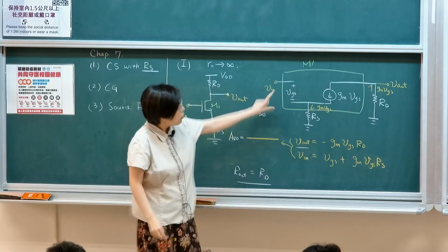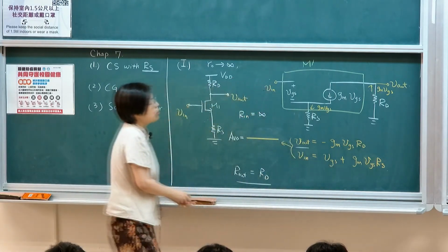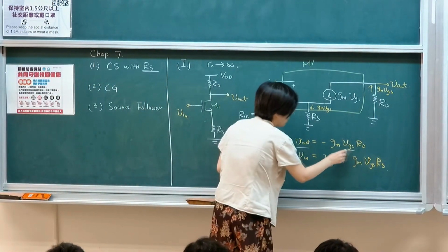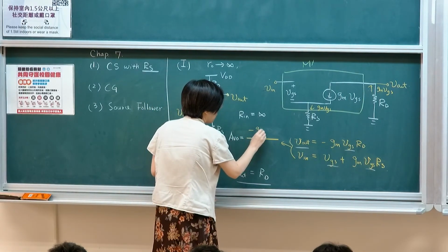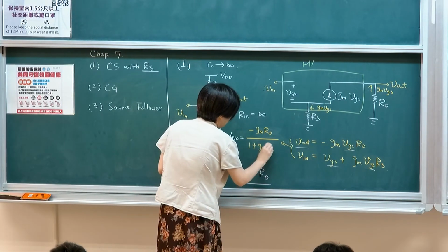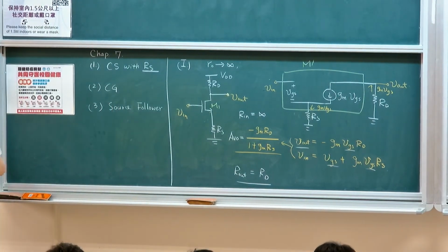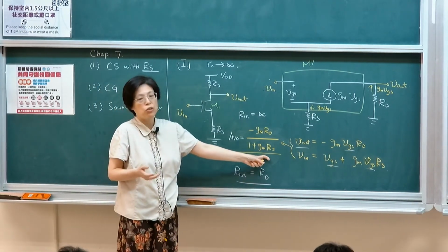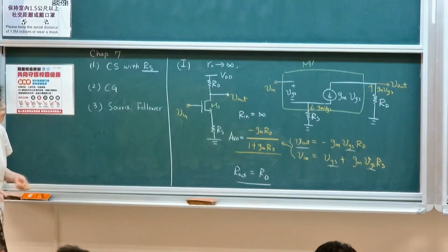After we eliminate V_GS, because both are functions of V_GS, the final result is the original R_D attenuated by a factor of g_m R_S. This looks very familiar. It's whatever happens when you have resistors. The attenuation effect is a factor of g_m R_S, or g_m R_E if you're using the bipolar counterpart. Okay?